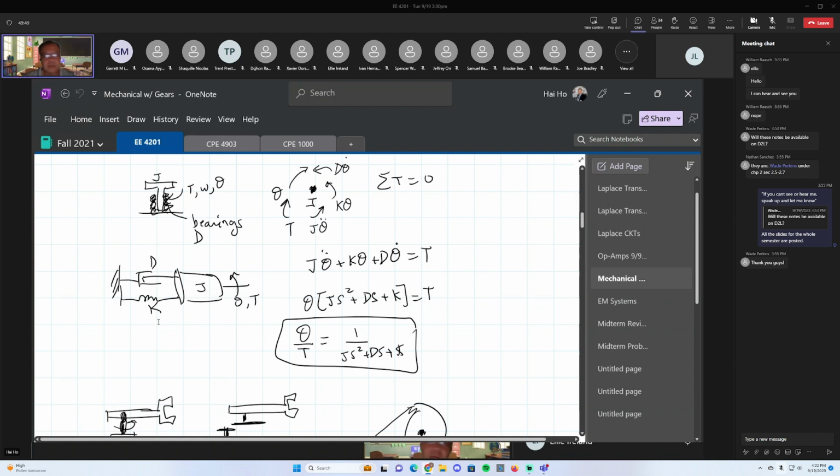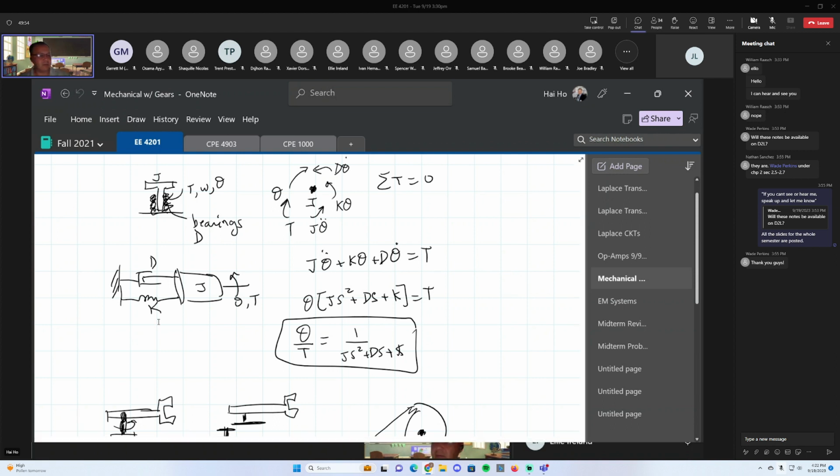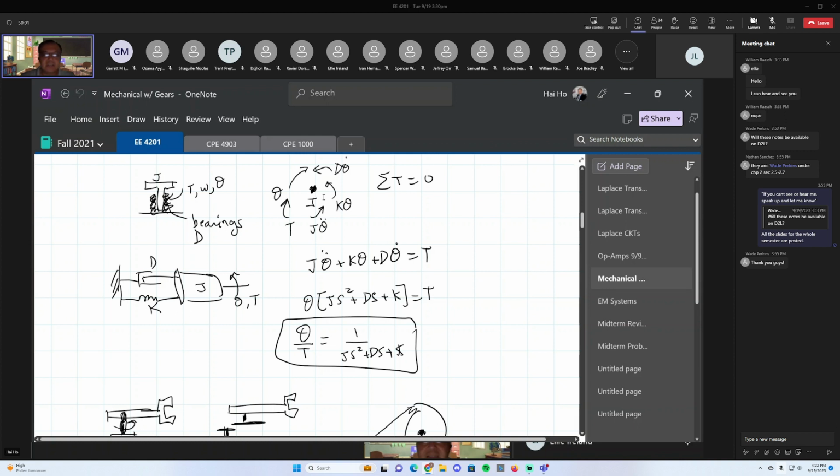Okay, so the way that you do the free body diagram of this is, think like you're holding the drill, and you look straight into the drill where the shaft is pointing to your face. So that's this dot here. This shaft has inertia sitting on it. It has some torque exerted on it, and that will create some angular displacement theta in that same direction as the exerted force.